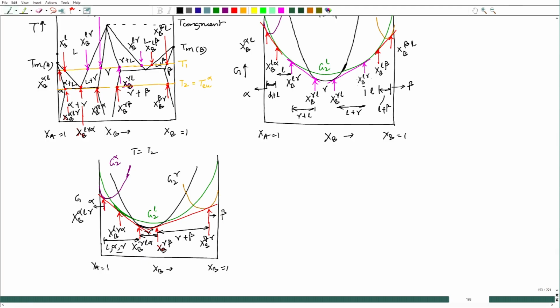So, that way you can actually draw the free energy composition diagram even if a phase diagram is given. This is a congruent phase diagram example, and congruent melting is a unique example. Why? Because you could see here that the congruent melting phase, which is gamma, has a melting point higher than the melting points of the pure metals constituting that phase diagram. If you try to see examples, you can look on the internet. One example is the aluminum calcium phase diagram, where we have a congruent phase which is Al2Ca.